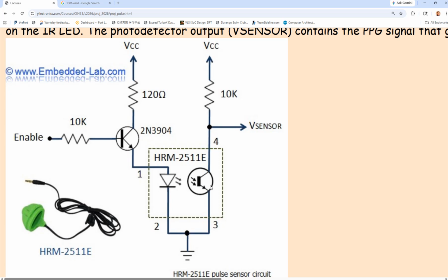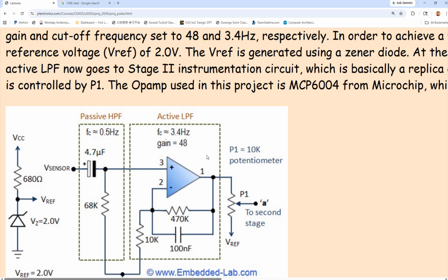which doesn't carry information. Maybe because it's lifting the AC signal, but anyway. So we're not looking at DC because we're trying to count the peak to peak, the time period between the two peaks, right? So you count many of them and get an average of it, so you can get a heart rate. But there will be a DC offset, and this is very common.